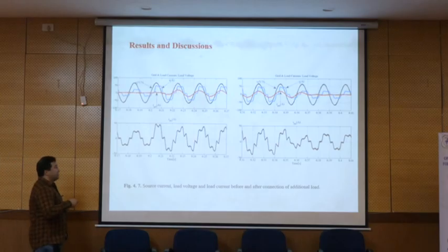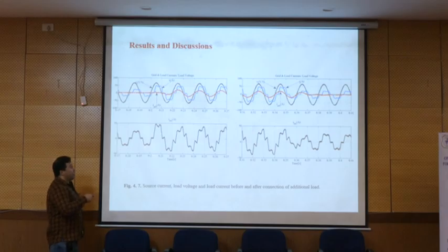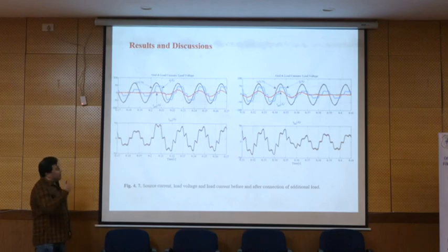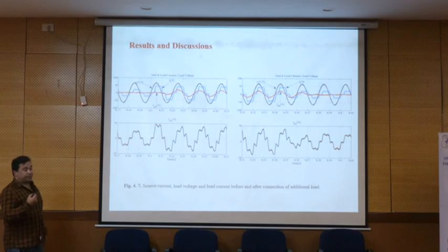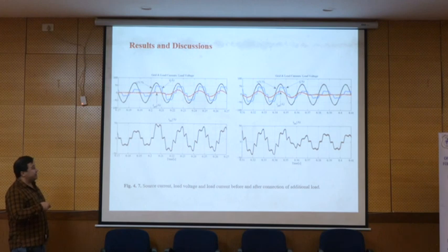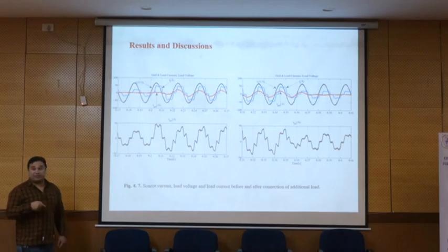So then we see that all the active and reactive power in harmonic frequency and also reactive power in fundamental frequency plus part of the active power in fundamental frequency is compensated here, and then the rest of the power, this red color, is coming from the